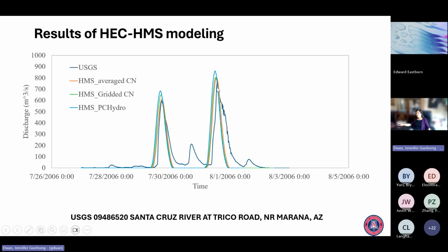Why? I said 2020 land, we have more developed urban area than in 2006. That's why we predicted more runoff than 2006. In 2006, we had more green space than today. But interesting, you see this old curve number, the old curve number based on 80s vegetation data, they also predict very high runoff. So this is surprising, but I don't have a good explanation.